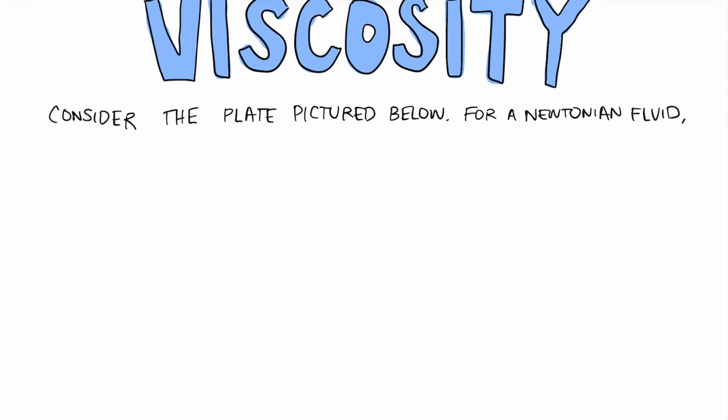If you, in contrast, think about something like quicksand, where the resistance of the fluid depends on the amount of shear stress that's actually applied to the fluid. So the more you struggle to get out of quicksand, the harder it is. That is typical behavior for a non-Newtonian fluid. But for most lubricants, it is a good assumption to say that they behave as a normal Newtonian fluid.